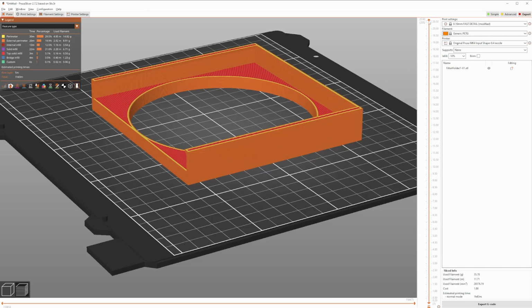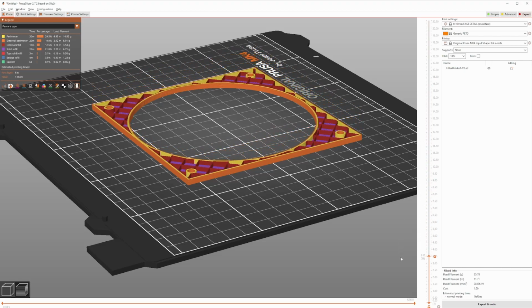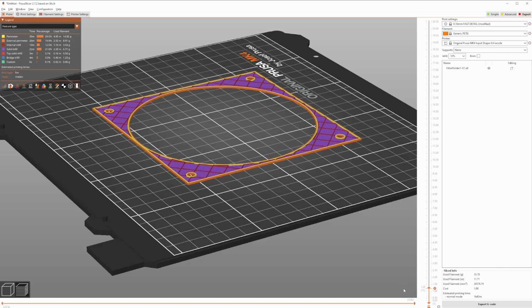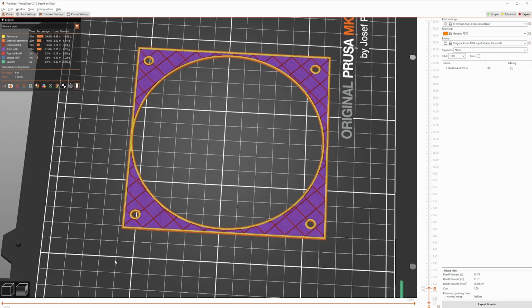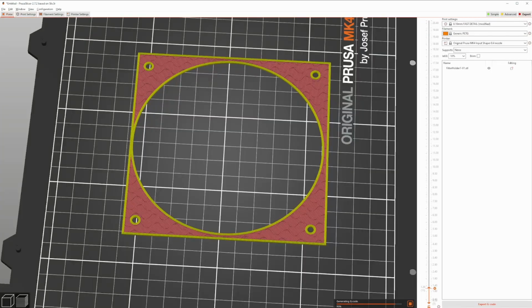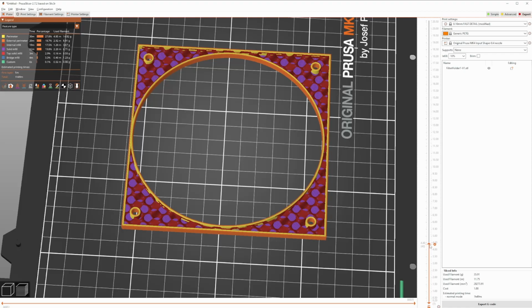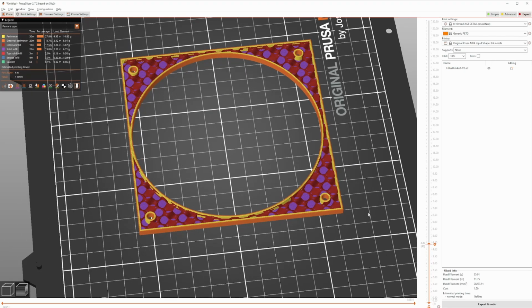Now we can go over here and bring the layers down to see the actual individual layers that the printer is using. And we can see right here we have the infill pattern. Now the infill is important because you want to pick something that's structurally strong. So in my printer settings, there's infill, and we have grids currently selected. And strong ones are usually something like a triangle or a honeycomb. And gyroid is also a really strong print type, and you can see it's just overlapping spirals that merge together, which creates really strong prints without using much filament.